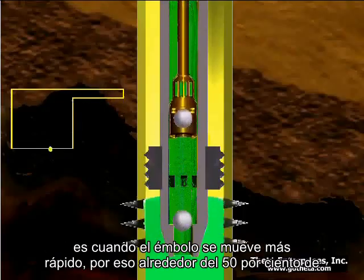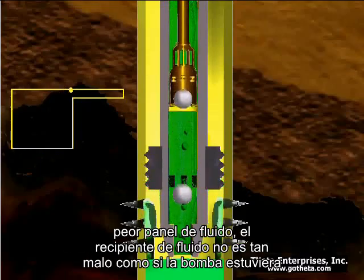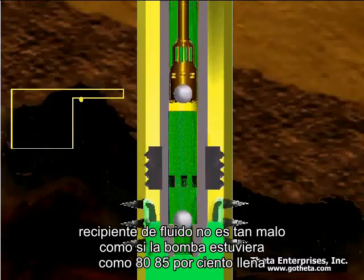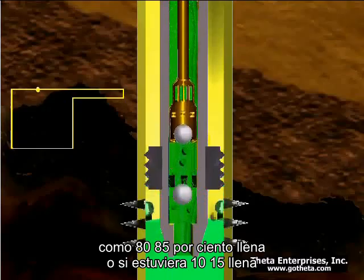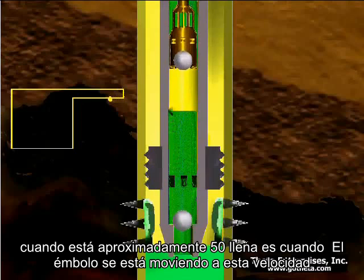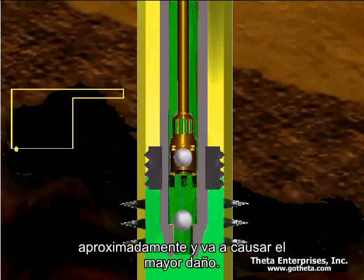So about 50% pump fillage is going to give you the worst fluid pound. It is not as bad, as far as the damage it does, when the pump is 85% full or 15% full. But when it's about 50% full, that's when the plunger is moving at its fastest, approximately, and it's going to do the most damage.